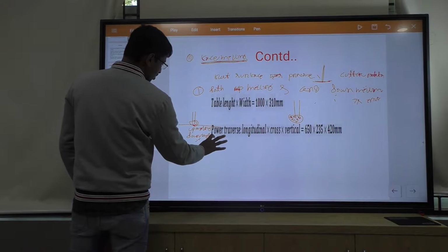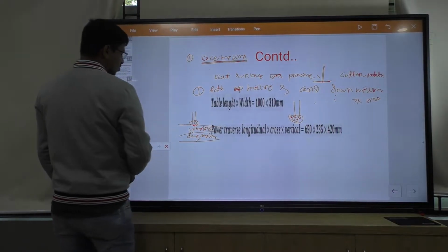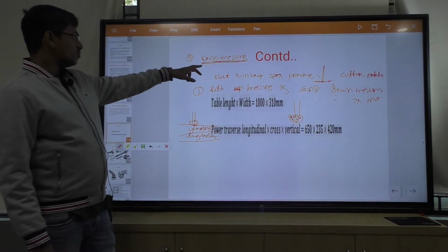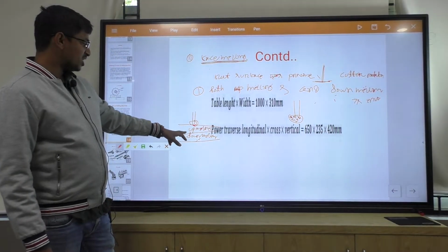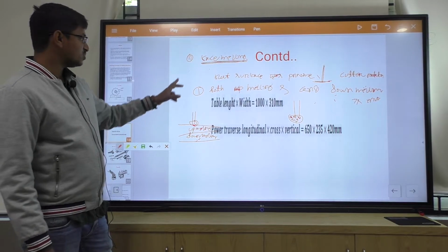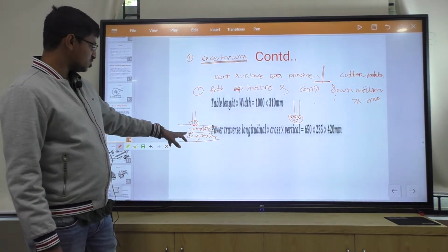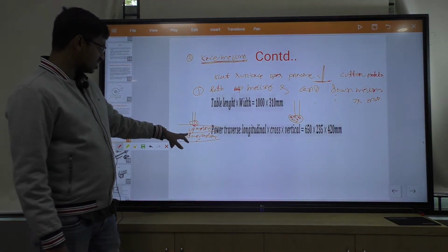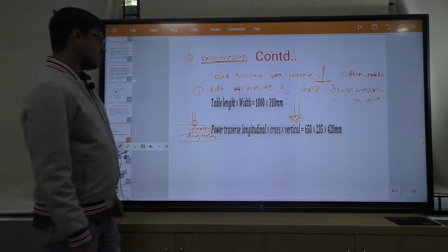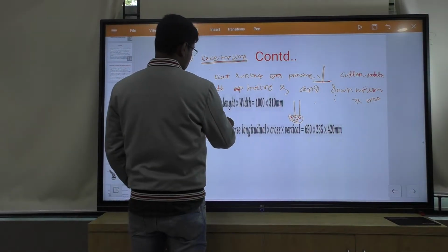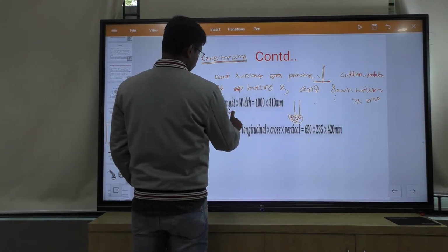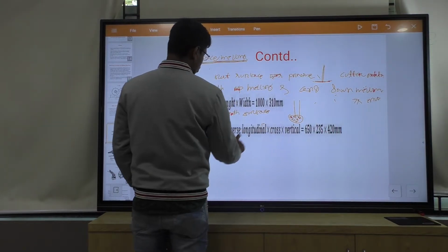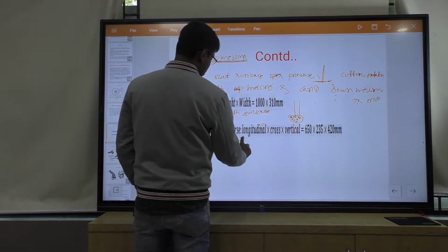As both up milling and down milling operations are used, face milling uses both advantages of up milling and down milling. A very smooth surface is produced, but the surface should be flat.